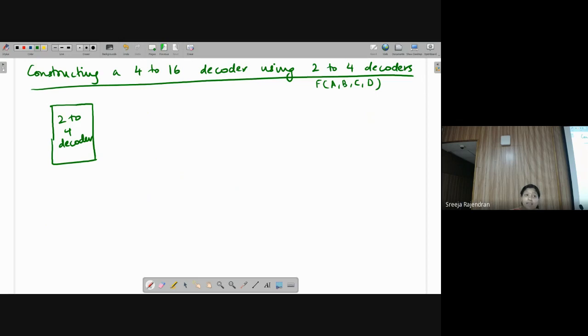We had select lines, and we gave the most significant select lines to the mux closest to the output. Here again, it's the opposite. So I will give the most significant variables to the inputs. Here I don't have select lines, so the inputs are connected to the first stage. So A, B will be the input here, and I have an enable G. So I have 4 outputs.